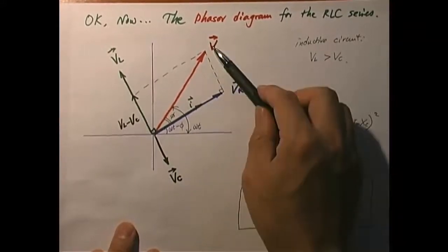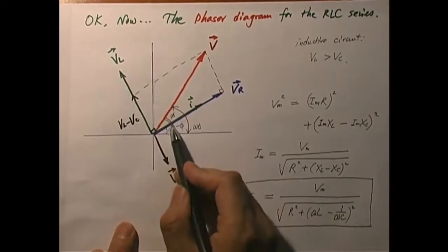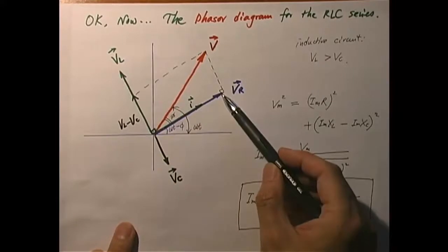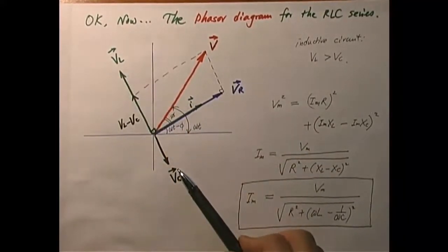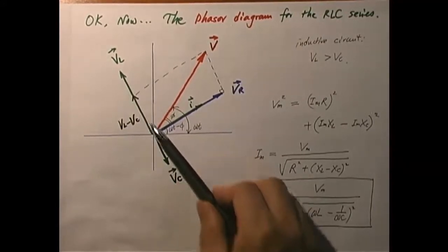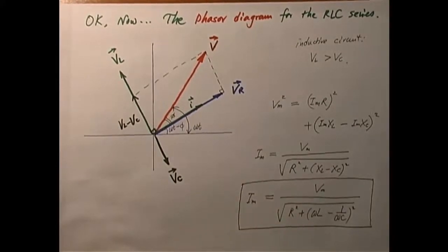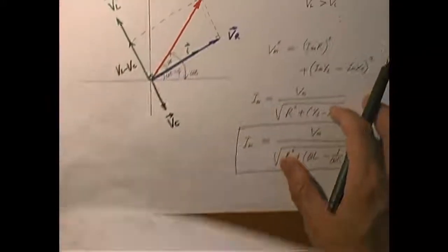And that VR should be equal to V. At that particular frequency, you find phi has to equal what? 0, because V, the EMF, and VR should be the same thing. VL and VC totally cancel each other out. They have the same magnitude, but exactly the opposite phase, or 180 degrees out of phase with each other. They always cancel out each other. We call this particular circuit a purely resistive circuit. That happens only when VL equals VC. Okay, so I'm going to write a special case.